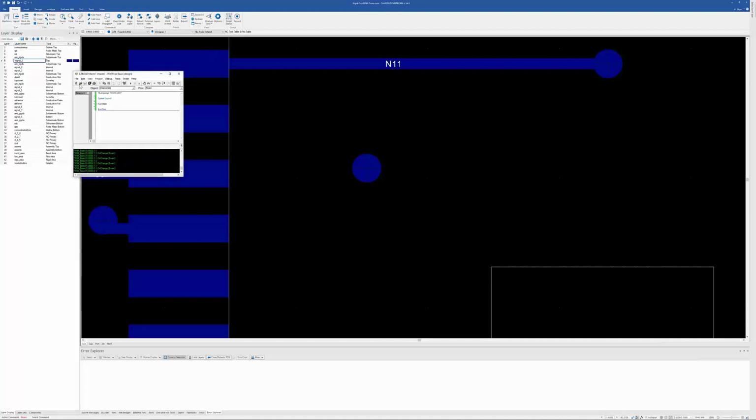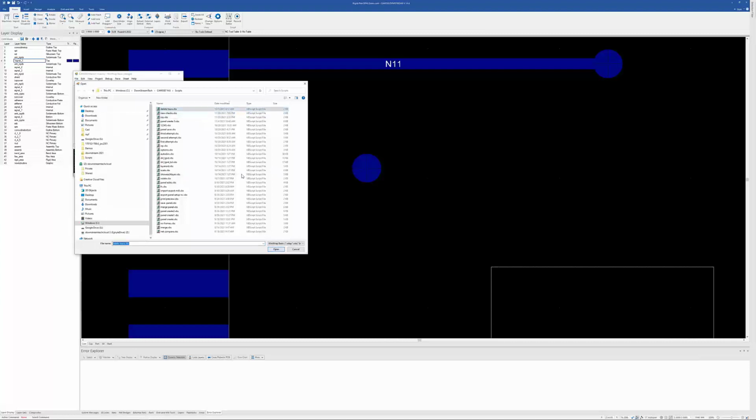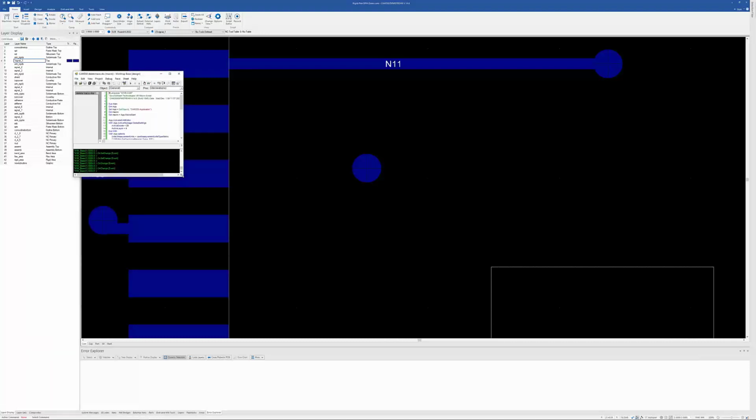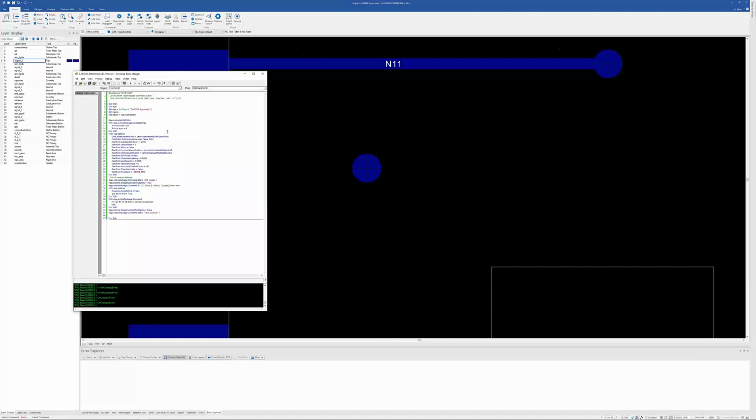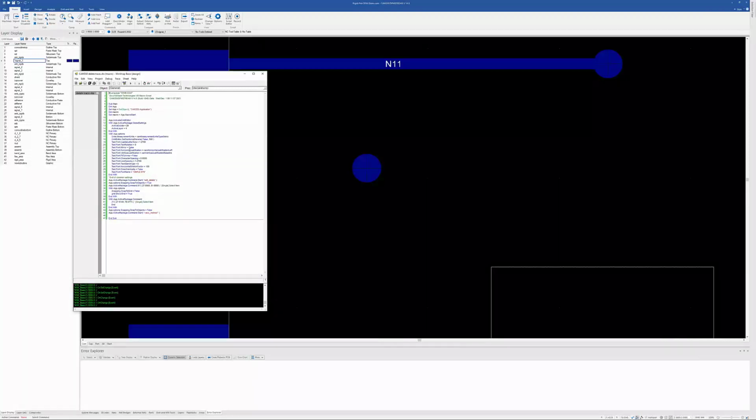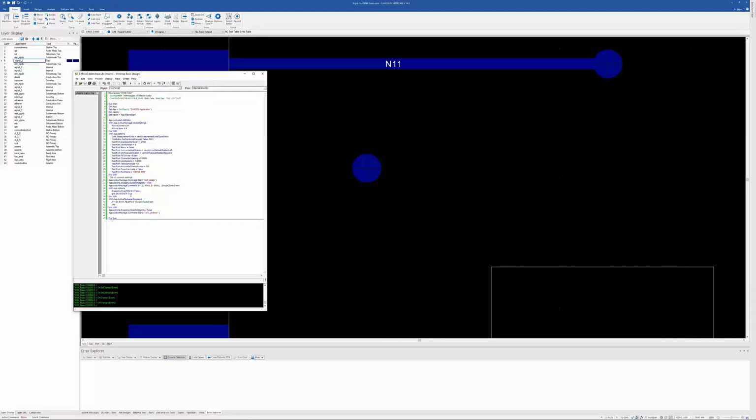And now we've recorded what function I did there in a script. If I go to the script editor, I can open up that script that we've just created. Let's take a look at it here, make this a little bit bigger. A lot of it is just environment. It takes a picture of the environment before we do that, and that's what a lot of this stuff is. And then you see I turned off the grid snap here, and then I turned on edit delete, and I selected a single item, and then I did a redraw on that. So basically that's what's in the script.